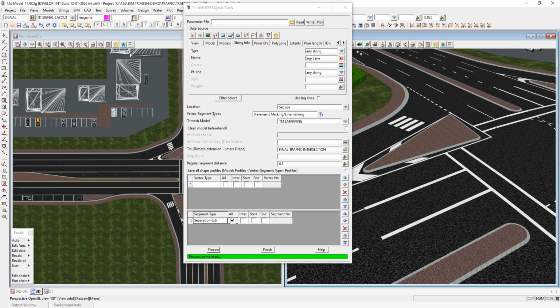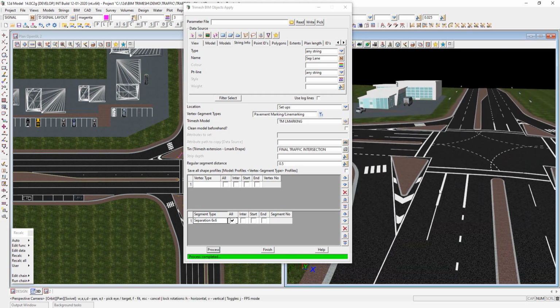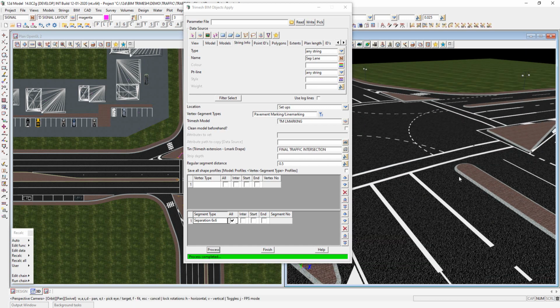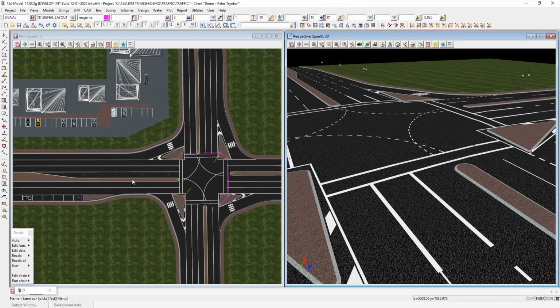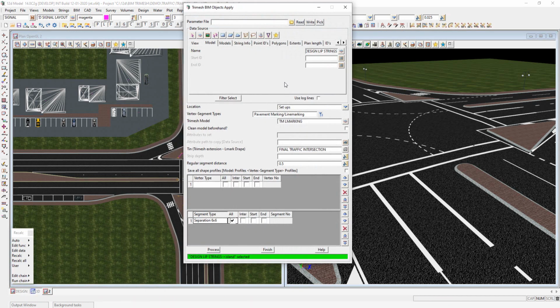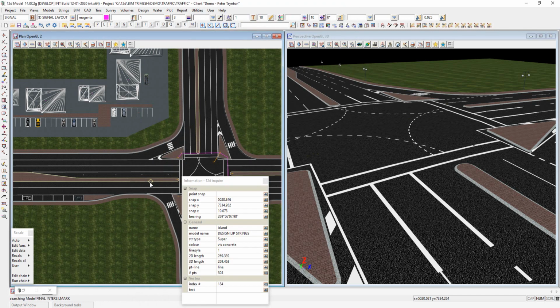If we're going to look at situations like our curbs and our traffic islands, they normally have a design string, which is the lip or the face of the median. So in that case, I'll put them onto another model, so I can go and grab those, and their name is, in this case, just called island.